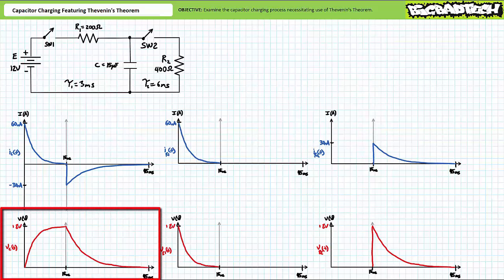Importantly, voltage across the capacitor, whether charging or discharging, never undergoes a disjointed instantaneous transition or sudden reversal in polarity. That's the point. Capacitors resist sudden changes in voltage and are often employed in circuits that necessitate relatively steady or slowly changing voltage conditions.